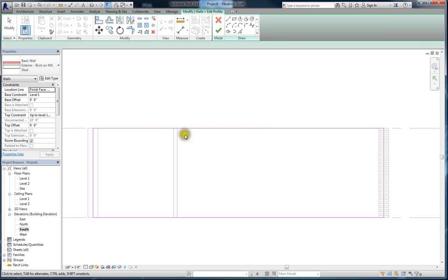So I click on that, and now the profile of my wall highlights in a magenta color. So now here I can start editing the profile with my sketch tools. These sketch tools, there's line, rectangle, and then all these other shapes as well. So let's start with line. I'm going to click on line, and then I'm just going to pick somewhere. So I can start drawing straight lines. Okay, that's one way. Another way is to do arcs. So let's say I select this arc, start and first point, second point, and then define a radius. Okay, so I want that.